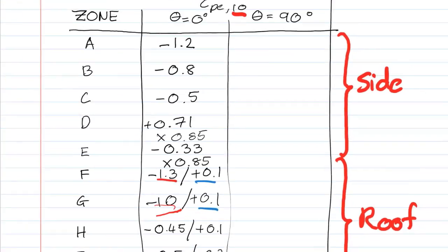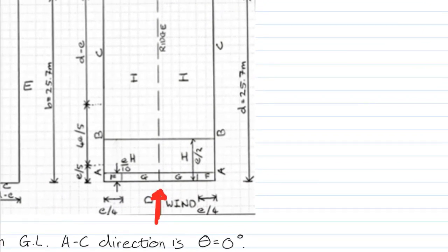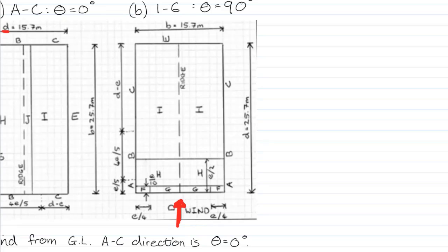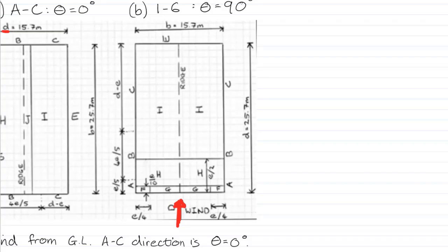in the other direction. So that is then when the wind blows, as shown here, from the bottom to top. So the building orientation stays the same, but what we're doing is we're shifting the wind pattern. So now the wind is hitting this gable face, so the gable face is that face there, it's with the roof profile on it, and the wind now, where it first intersects the building, that is our zone D.